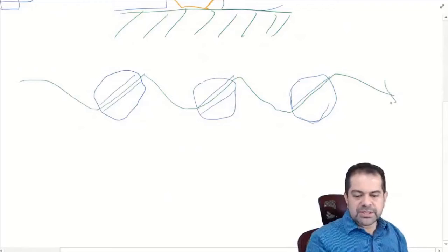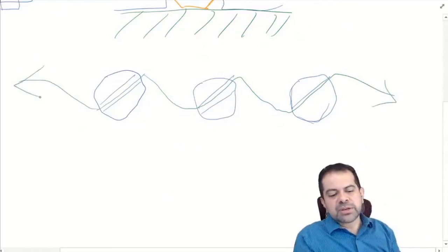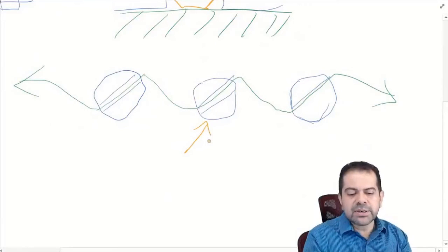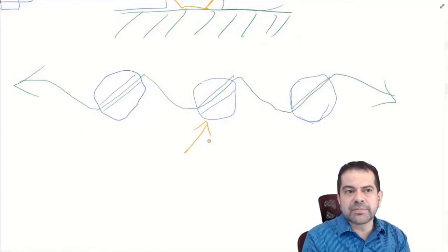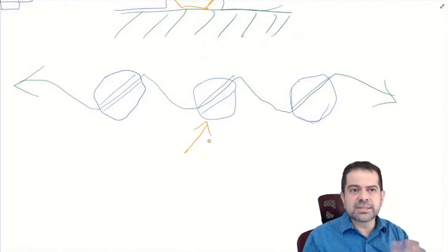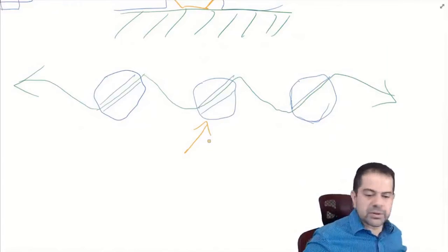So now you can see the wire will be under tension, and let's say this guy wants to go counterclockwise. It can't. If we try to do it, it's going to tighten the other two in a way, and it just won't be able to back out. Okay, there are dozens of mechanical ways to secure screws.